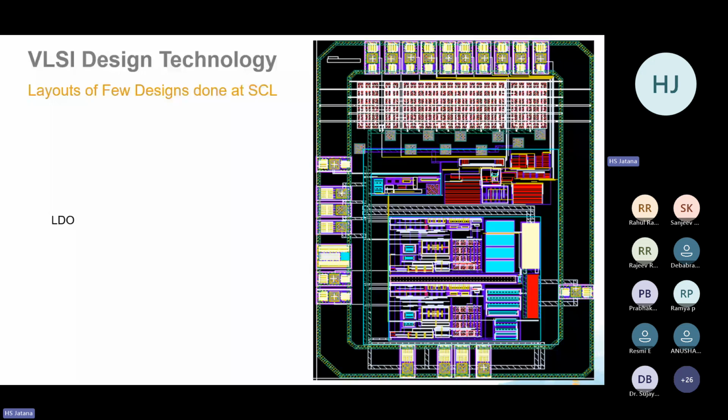So these are the IO pads. Here you can see this black. This silicon is not used, so there it will be dummy. You will do the dummy fill here. Some dummy structures will be put, and the tool will do it. And there is a rule on how to put those dummy layers.